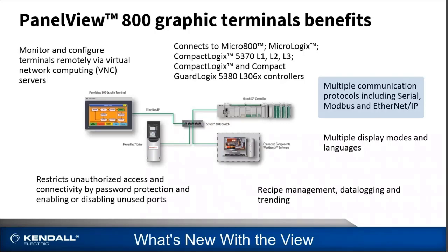They communicate with multiple protocols, including serial, Modbus, and Ethernet IP, which means they can connect to almost any controller. And they have recipe management, data logging, and trending. We can use USB and micro SD for that. And we can connect remotely over VNC.